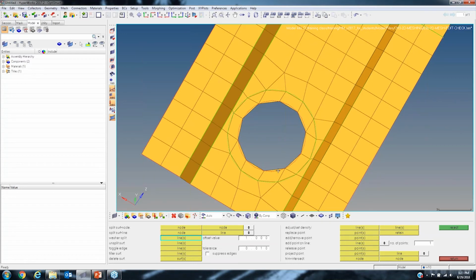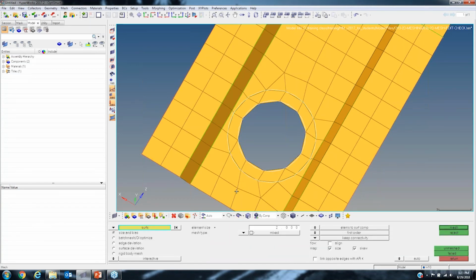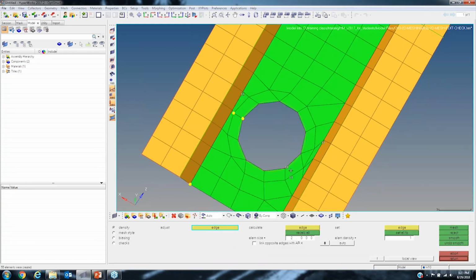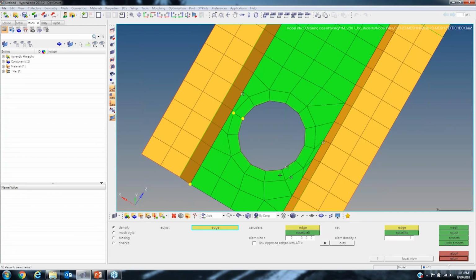And this is very important for when you're trying to generate meshes that have holes, or you're trying to have parts that bolt up together and you're going to attach together. And I'll show you guys on tomorrow's training how to simulate bolts and bolt connections between meshes. But for this here, if we go ahead and try to remesh this now, we can just set this value to the same amount. I'll just do 13 actually. And you'll see that you'll have a nice row of elements that goes around the circle here.